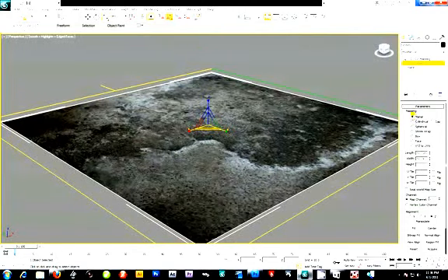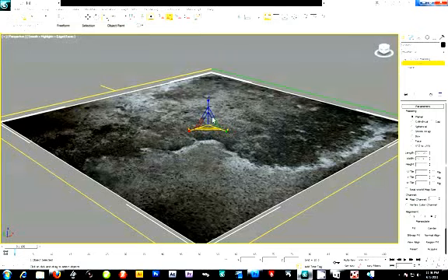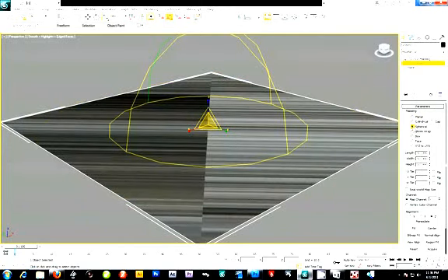But notice down here in the gizmo form, you have mapping. If I click on UVW mapping, there's the orange bounding box. When we're in gizmo, it shows it in yellow, and where the center point actually divides the green line. This is a planar, so technically we're just going to leave it at planar. But what if it was a cylinder object? You would use cylinder. Spherical, you would use spherical.